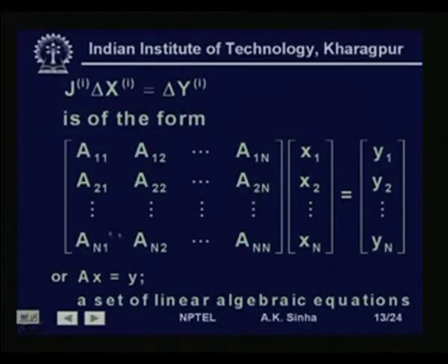So, if you see, the Newton-Raphson solution method finally boils down to solving a set of linear algebraic equations. That is, a set of nonlinear algebraic equations are being solved as a set of linear algebraic equations, where we are linearizing the equation at each and every step of iteration.